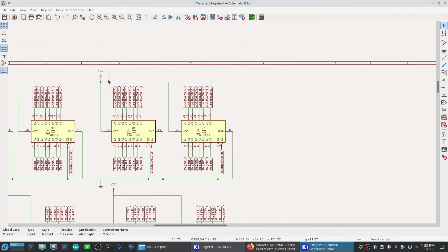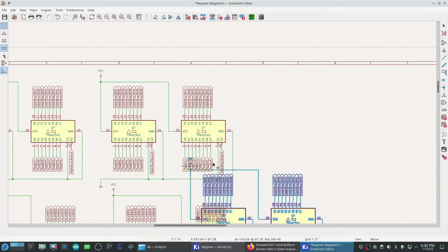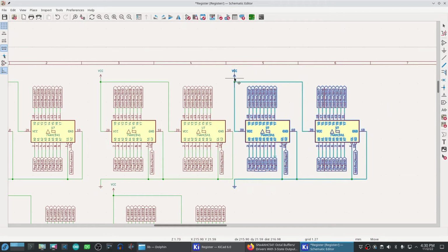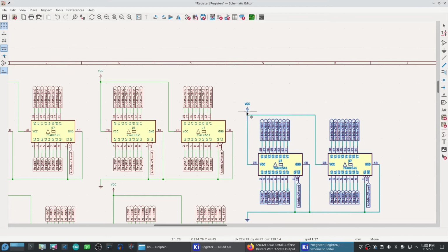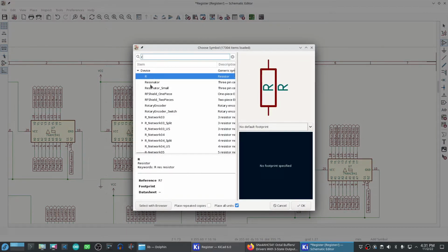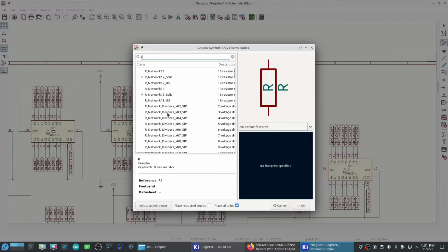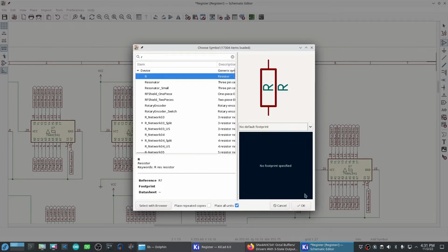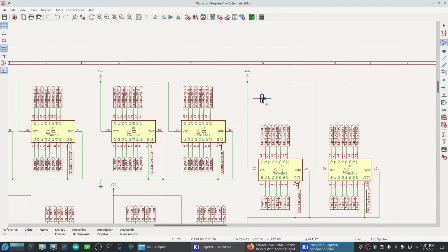Now I need to create the line drivers and LEDs for displaying the current registered contents. I do this by copying address bus 2 and then start making the changes. Now in the last video I mentioned trying to use the grab feature versus the move feature. I do this moving the VCC line up to give me some additional room for the LEDs and for the resistors that are required, the current limiting resistors. And as you saw, that worked quite nicely.